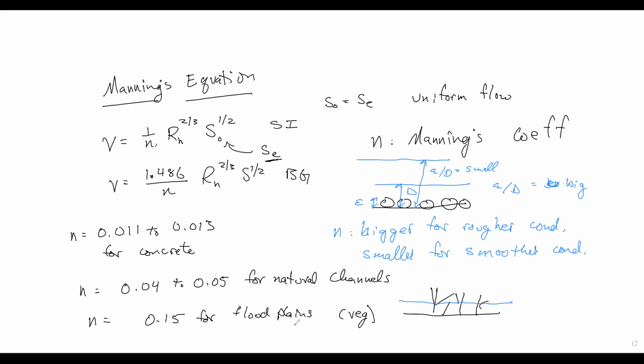So there's a table in your book for natural channels. It's different than the table for closed conduit pipeline. So we'll be referring to a different Manning's n table for this class. I like the Manning's equation and this coefficient. It's in the denominator, and so that means when you have a high Manning's n value, you get a lower velocity value. So rougher condition, slower velocity, greater depth. Low Manning's n value, faster velocity. So that's how that works. And for me, that's a little more intuitive. High means rougher, versus the Hazen-Williams coefficient, which is the opposite.